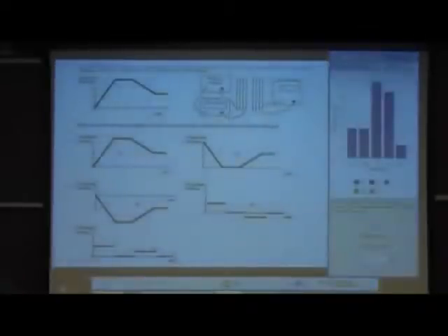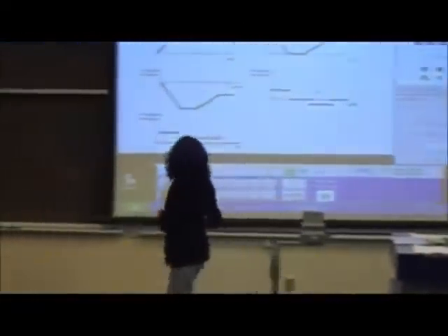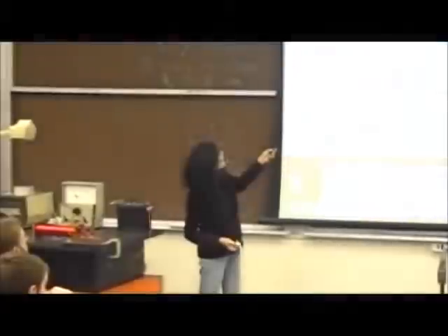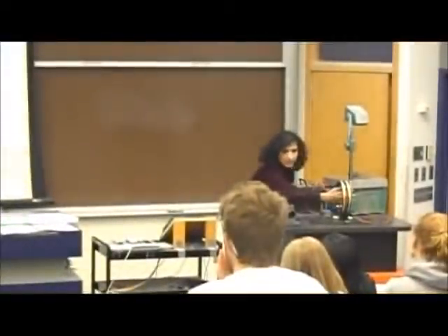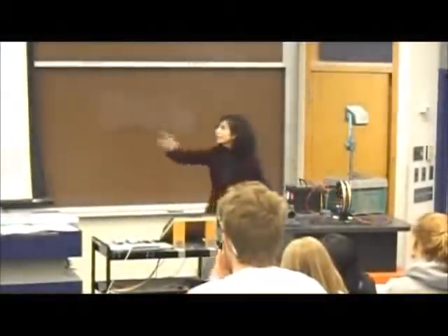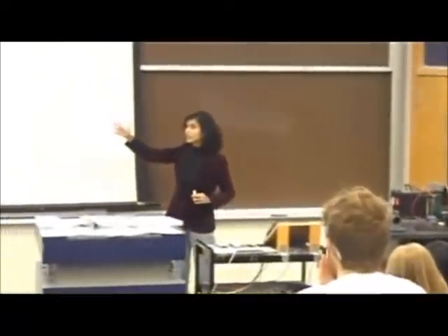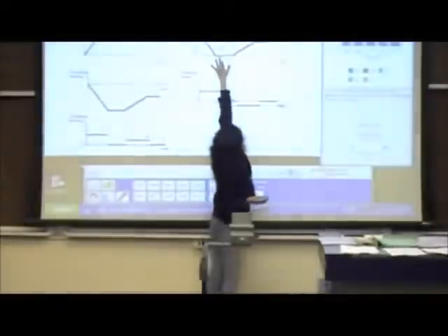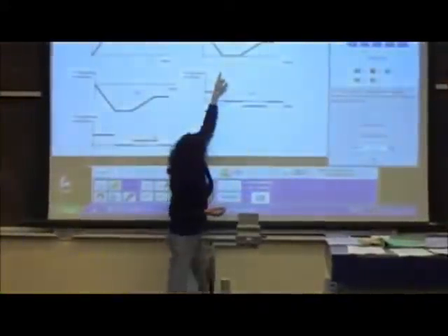All right, great. So one thing that you have to understand here, first of all, is the easiest way to rule out some of the possibilities here is to see, look, if the current reading is constant here, that means the flux that is produced by this current, for the period of time the current is fixed, wouldn't the flux be constant through both loops? In that case, will there be any d phi over dt over that period of time? No. So one thing you know for sure, the EMF induced should be 0 over this time, from this time